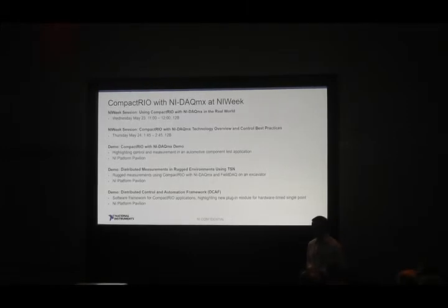We only use four slots, and they want to allow their customers to plug in relatively any I/O module. I've found ways to do it, jumping through various hoops in hybrid mode, but it's not very easy, especially detecting what is in there right now in a programmatic method.